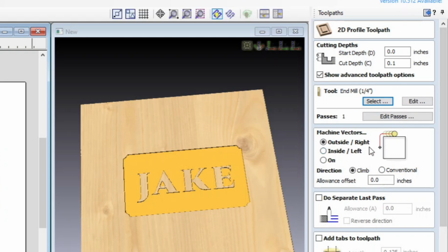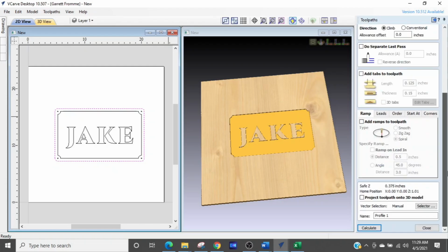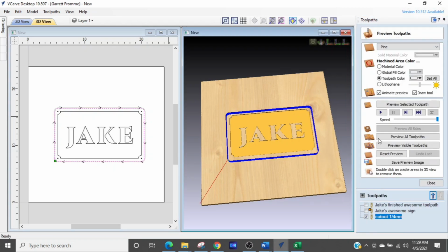And we're going to be on the outside up here. We want our cut depth to be the full depth. So we're going to say Z equals, and that set us up. And then we're simply going to run this. I could call it cutout. Just always name your stuff. Cutout. And then I keep forgetting to tell you, put in the router bit you're going to be using, because that'll show up in the program name, the G-code name. Click calculate, run the toolpath, and there we go.